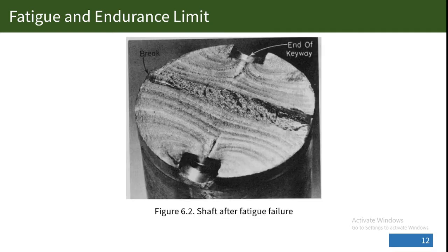Seen in figure 6.2 is a shaft after fatigue failure. We can see here a break at the cross-section and some progressive cracks near the two ends of the keyway. These cracks, if not attended to, will eventually progress into a larger crack, which would be detrimental to the performance and safety of the machine.